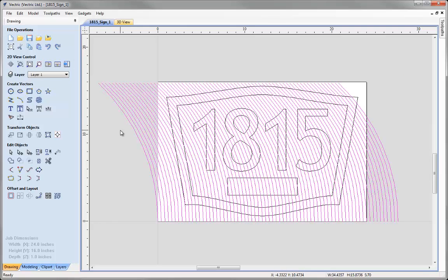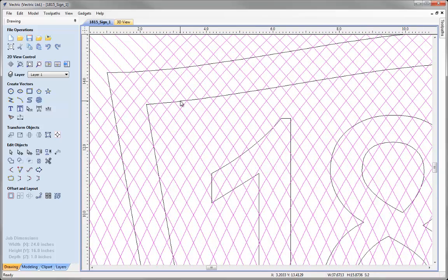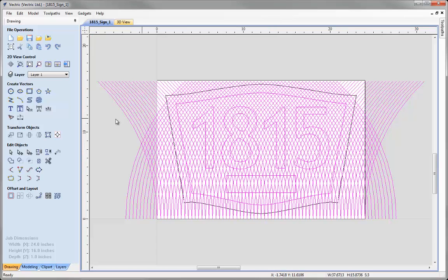I'm going to hit G in order to group those together, and I'm going to hit Control, Shift and H in order to create an opposite copy of them. Now I'm going to select both sets of those vectors there. I'm going to carefully come in and zoom in and select this group here. Let's just hit F to fit again there, and we can look at another new function here, trim selected objects to a boundary.